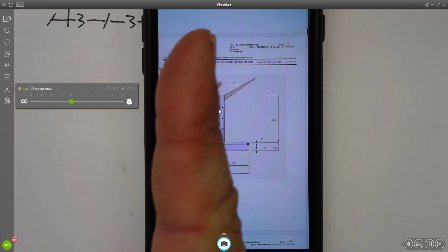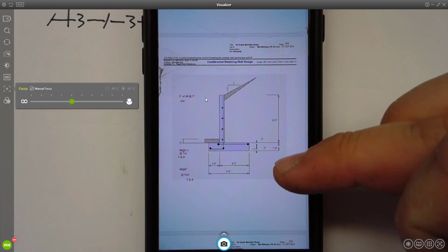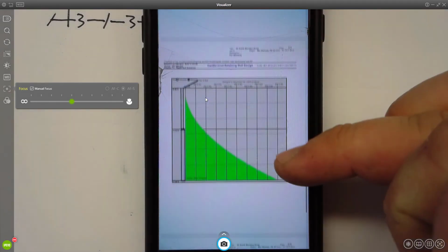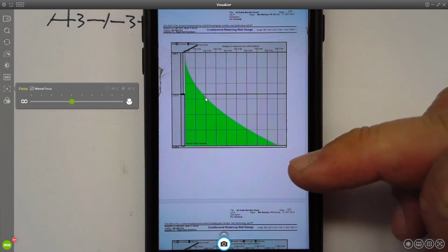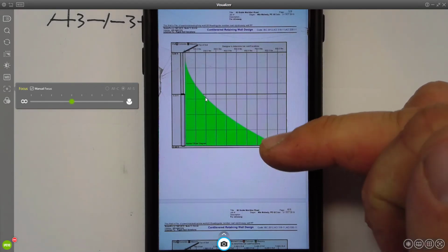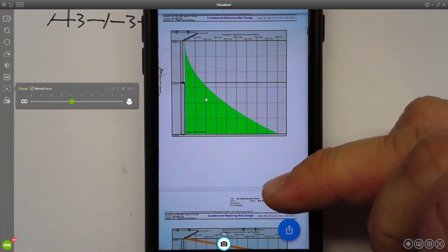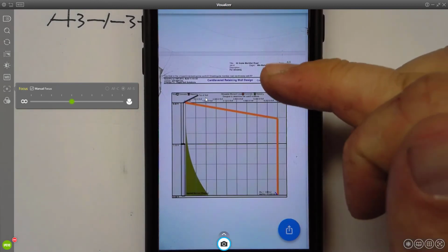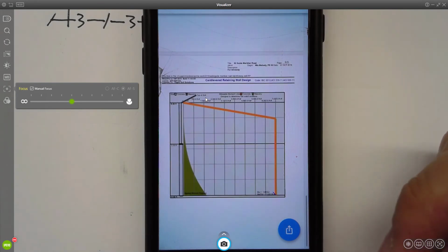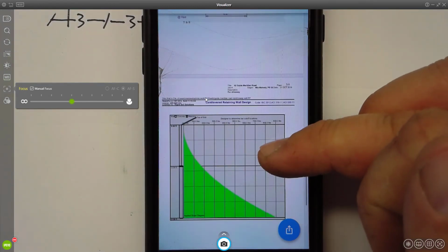So if you look at this, there's a force loading it that's trying to make it tip over. And so what the designer has to do is come up with what the bending moment is on that as you go through the wall. And so it's showing that the bending moment, actually, what's that say? This is the applied shear diagram, it says. So that's the shear on it. And here's the applied moment diagram. Okay, so shear and moment showing what, and again, in this case, the beam is standing straight up and down instead of being horizontal, right?